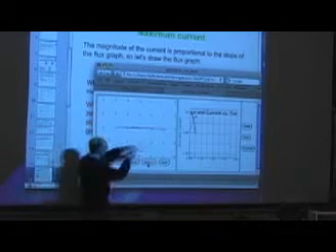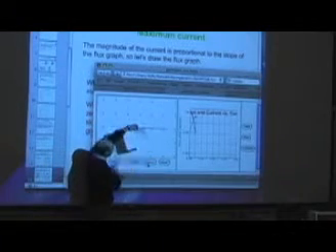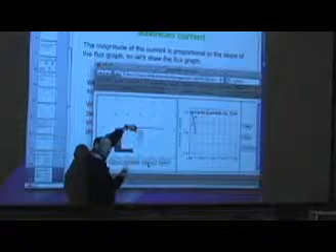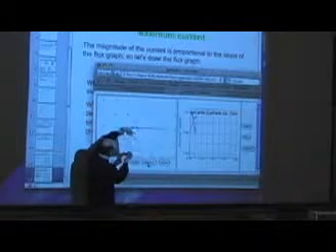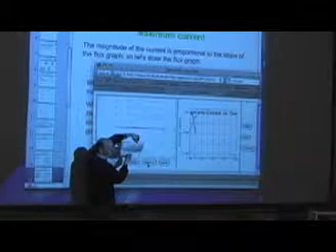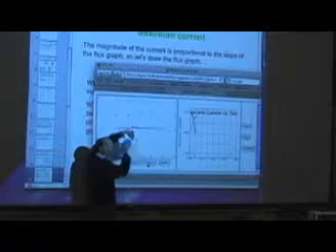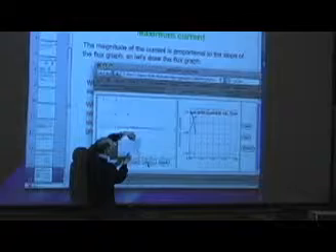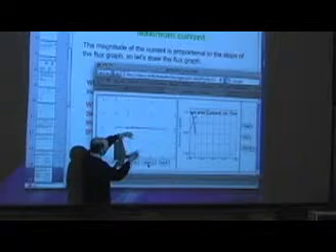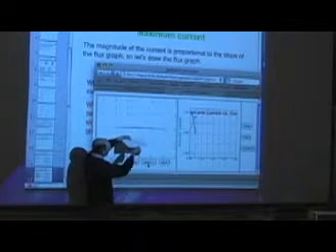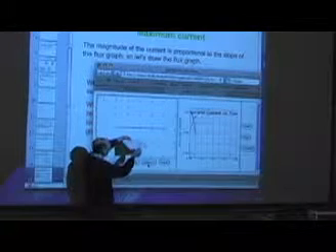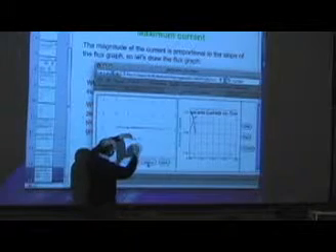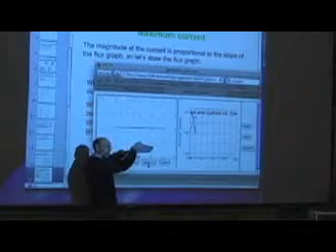So why is that? When it's in this orientation, the current is 0, because as it rotates through that orientation it's just not changing flux there for an instant. It's reached the peak of the flux graph. But here, as it passes through this orientation, you're changing from field lines going one way through the loop to field lines coming the opposite direction through the loop.